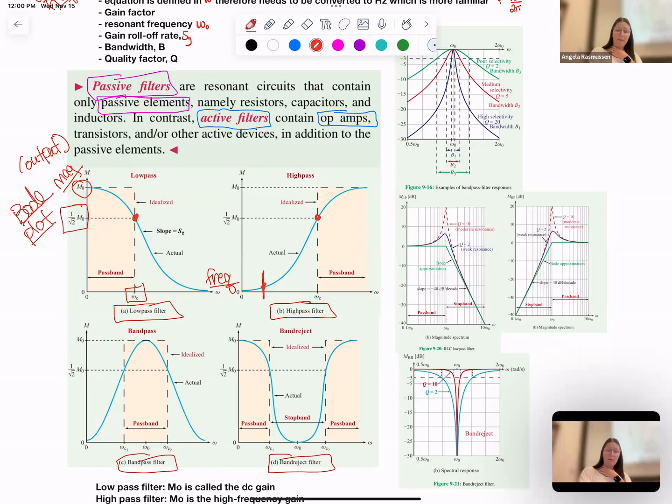So cutoff frequency or corner frequency, this omega C. What was the units of omega? Radians per second. Okay, good. Radians per second. And high pass is then, once I reach that corner frequency, everything above it, I consider it as operating correctly and that is where the circuit operates. So I would call this that the circuit operates at anything above that frequency. Low pass is it operates anywhere below the corner frequency.